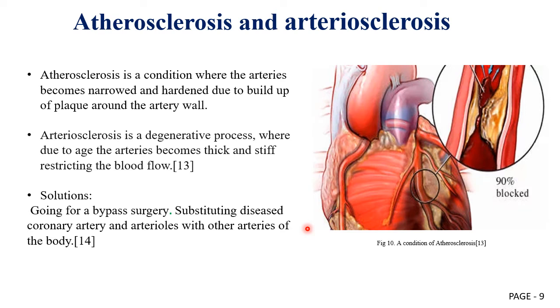Now the Hagen-Poiseuille equation, which all of us chemical engineers know very well, is very much applicable for blood flow. So what really happens is, for a constant pressure drop, the flow rate is directly proportional to the fourth power of the diameter. Now, for example, let's say someone is running. Suddenly, someone has an emergency. He or she is running.